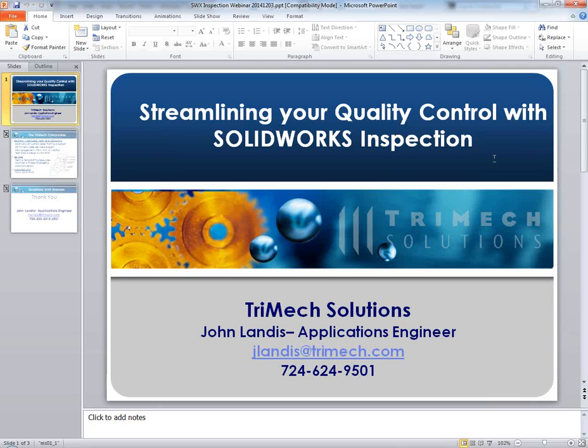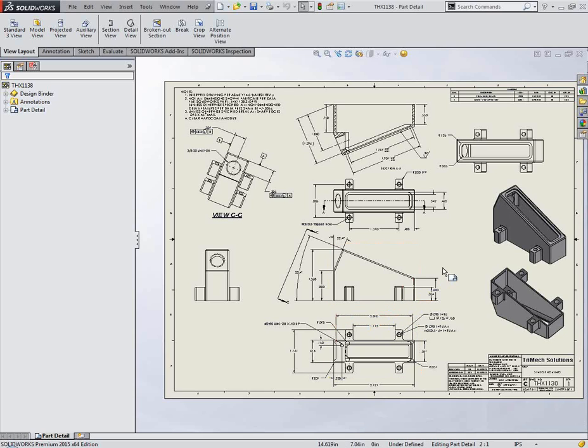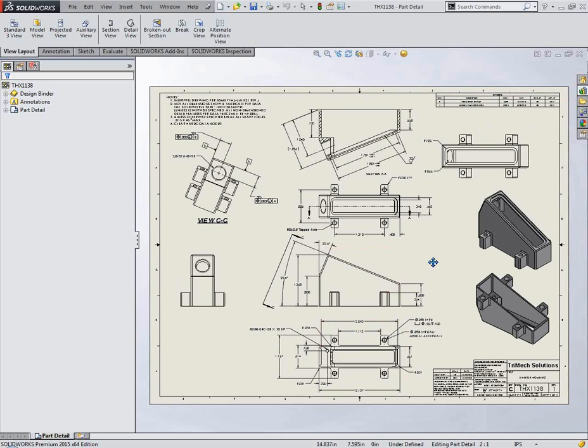So, in my experience, inspection in many different organizations consists of basically taking a paper drawing and then a Sharpie and ballooning out the drawing as required, and then having a companion document, either a first article inspection report or a homegrown inspection report. In a worst case scenario, this inspection report is a piece of paper. In a best case scenario, it may be in an Excel spreadsheet. But for all but the simplest drawings, creating this document package of a drawing with balloons and an inspection report with assigned lines is a very tedious process. It's a manual, tedious process.